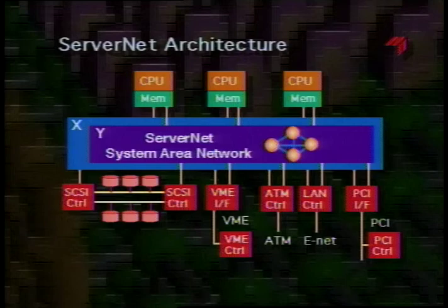The adapters don't require much more hardware than just the peripheral interface chip along with a single chip adapter into the system area network. Notice that with this architecture, all the scaling of both I/O and CPUs can be done through expanding the number of connections to the system area network. So it's a single place to concentrate the requirements for scaling a network and a single place to concentrate the fault-tolerant requirements, for instance for hot plugging devices for online service of CPUs or peripherals.